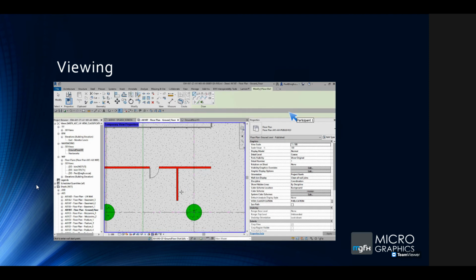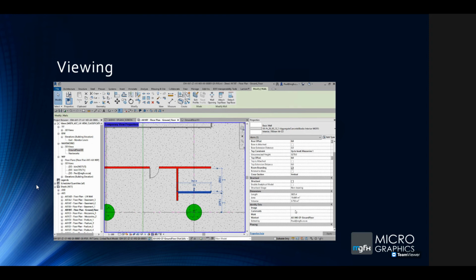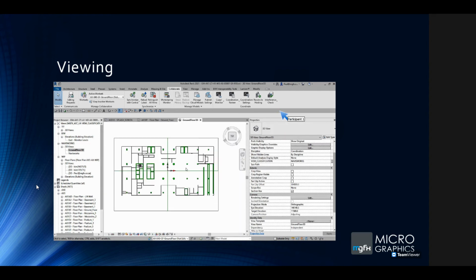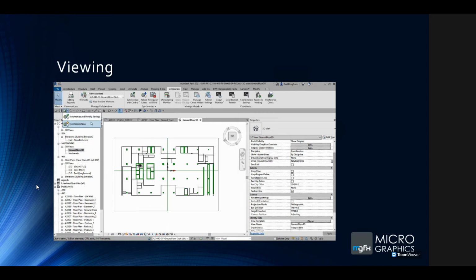And one can even put them in different phases. So the different phases, they don't really show up because this is how it's going to print. Okay, so it's maybe a good thing to see as well that if you change the phasing of that view, then you're not going to see that within the drawing comparison. But if you do a model comparison, which you can also do, then you will see the difference. The model comparison is what we do within the design part of BIM 360, and that's not part of this webinar, but it is possible.